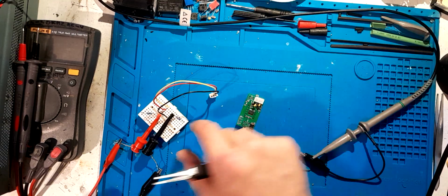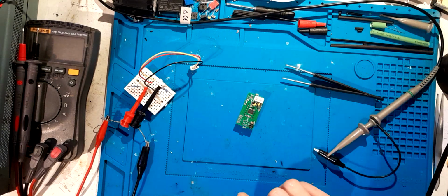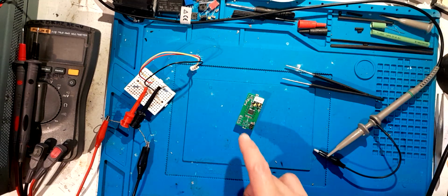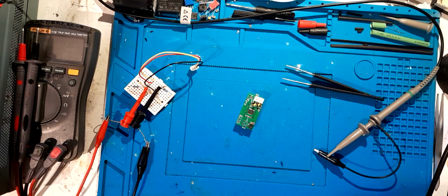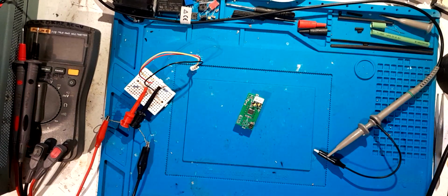I'll go get that diode and I'll put the diode across the regulator just in case, like I said. Actually, the diode will go across those capacitors because they're on the output of the regulator. For this, I'm going to use a surface mount diode because I can just pick the power diode that will sit right on top of the capacitor.